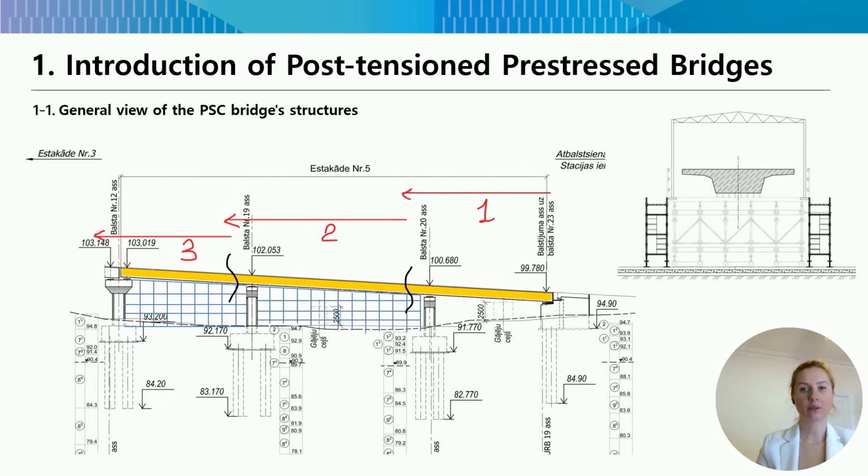Now let's consider the technological sequence of construction works, because it will affect the final internal forces in the structure. The sequence includes several stages. At the beginning, we install scaffolding, assembly of wooden and metal formwork to hold the structure. Then, construction of conventional reinforcement framework, and layout and installation of ducts and high-strength reinforcement cables.